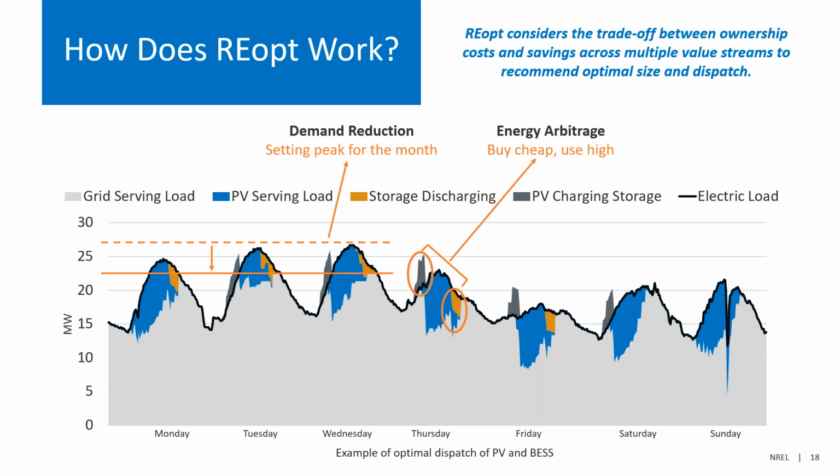So you can see in the horizontal set of lines a case where the PV and battery systems combine in order to reduce the peak demand and reduce peak demand charges in the utility bill. And then the orange and gray demonstrates load shifting, or buying energy when it is cheap, and then discharging the battery when it is expensive.